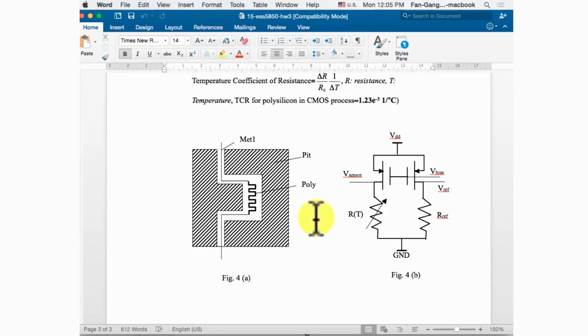Remember, silicon substrate is a very good thermal conductor. Okay? So when you have current going through these two resistors, even though they are the same originally, with the same resistance, for example, 1 kilo ohm for each. However, after you put the current into these 2 devices, this one will be cooled down by the substrate.